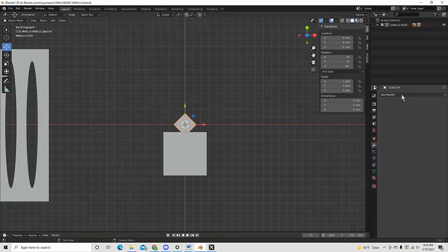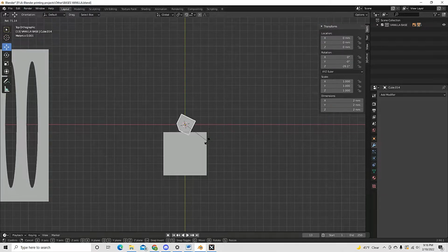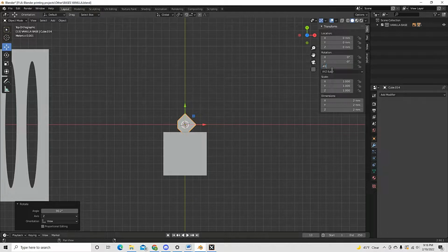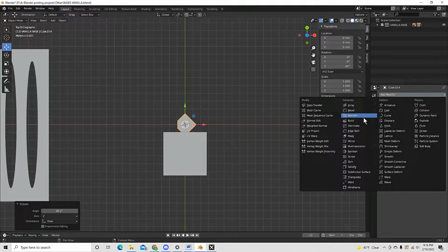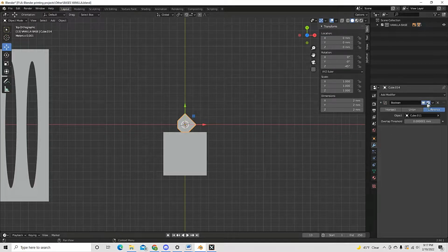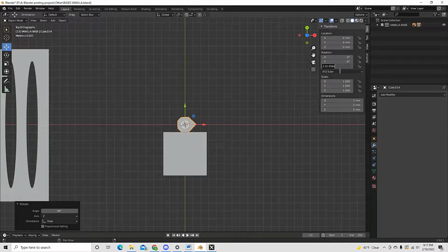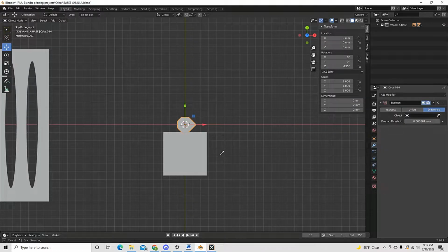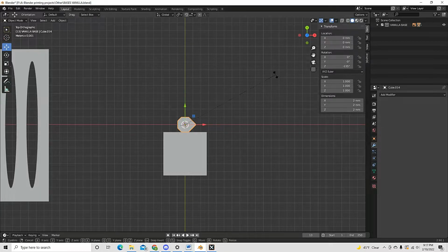Yeah, that's good enough. All right, take this boolean and apply. All right, let's rotate this again to minus 45. All right. Minus 45. Alright. Then boolean. And rotate again. Okay. Minus 135. Perfect. Boolean. Cutting this sucker pretty well. Rotate here. And then minus 225. Yes, perfect.